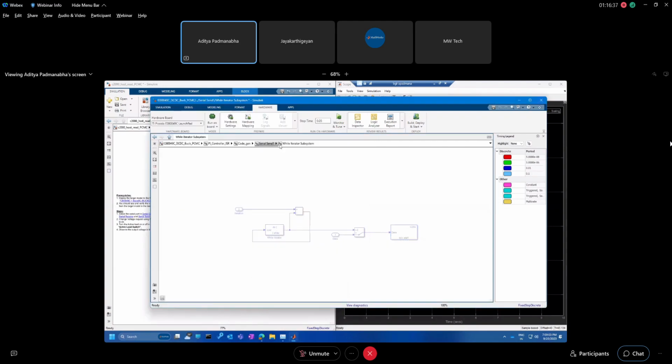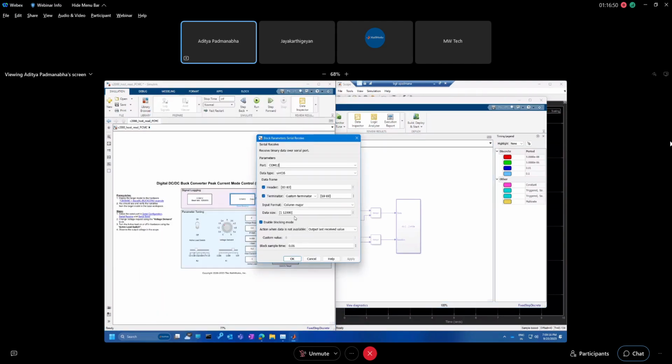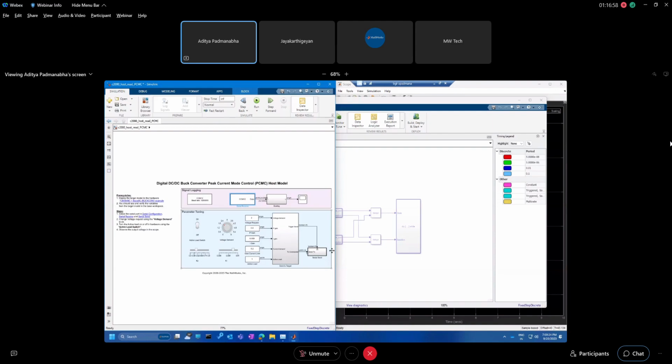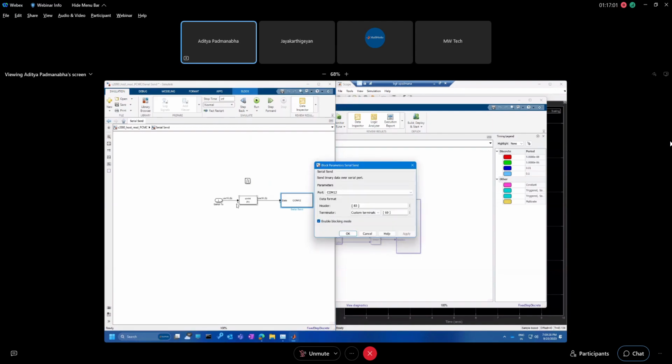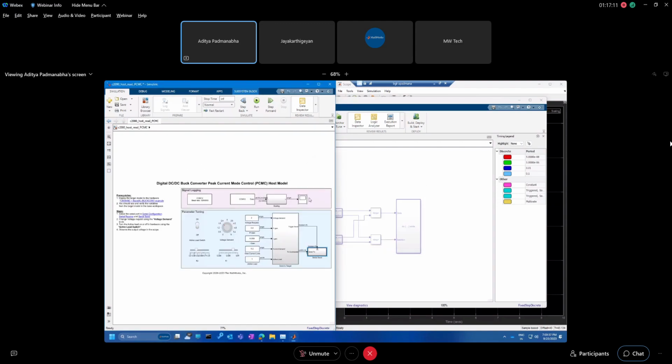While sending, I was sending in a while loop, as I mentioned, with the counter value from 0 to 1200. So I am receiving that much size of data with the sample time of 0.06, considering the rate at which we are running the serial transmit. And here I'm sending 5 data points, 5 uint16 which translates to 10 bytes, plus header and terminator. So this communication happens through the COM port from the target to the host, and that's why we are able to see the data.